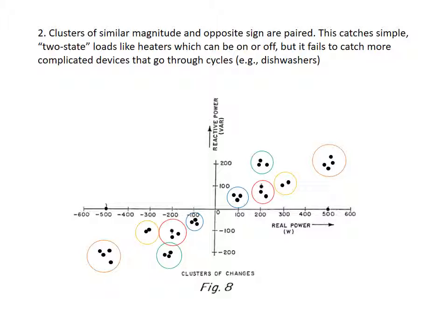So the whole point of that, the description of real and reactive power, is to give you some idea of what reactive power is, and we quantify it in terms of VARs as opposed to watts for real power. And so different devices are associated with different levels of real and reactive power. Again, I mentioned the purely resistive loads, so like lights or incandescent lights, heating elements, and toasters and ovens are associated with purely resistive loads, so they don't have any reactive power, they're just real power.